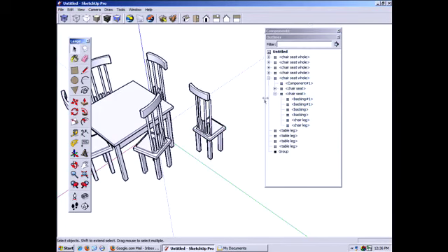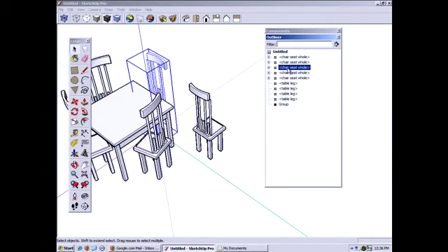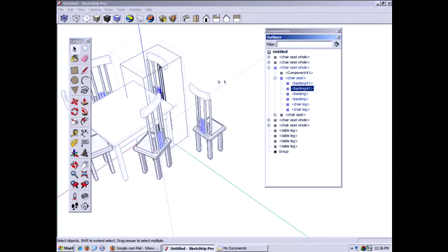Okay, so I'm going to collapse this. If I said I want to select, and you see there's 5 instances here, but I can select any of these, it shows that. If I expand it, I can get directly right into, without double clicking and stuff, I can dig right to that very one I want through the outliner. That's one of the advantages of the outliner. There's others. But the outliner shows your hierarchy of nesting, and we'll talk about that as well.